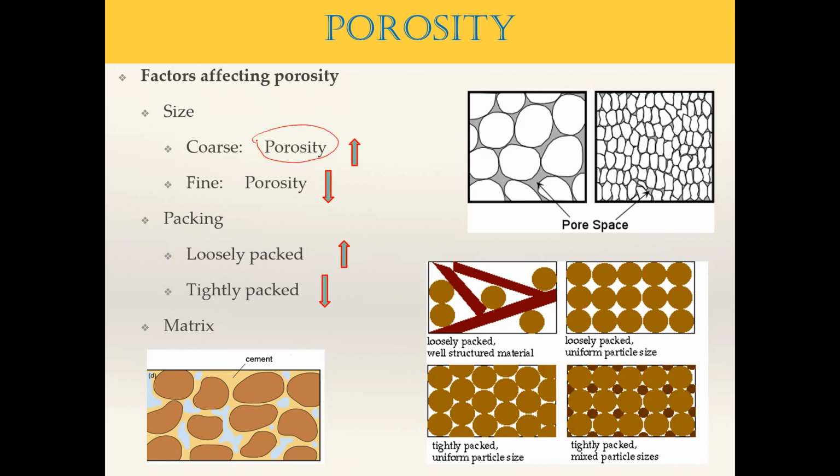What is the definition of the porosity? That is the volume of the void over the total volume of the aquifer. Right? So if you consider an aquifer formation like this, these are the voids. So this is where the water is stored. Right? So the porosity is an indication of how much water we can store there. Now, when the particle size becomes higher, with the coarse particles, a large amount of water can be stored. For example, gravel. Gravel can store a large amount of water.